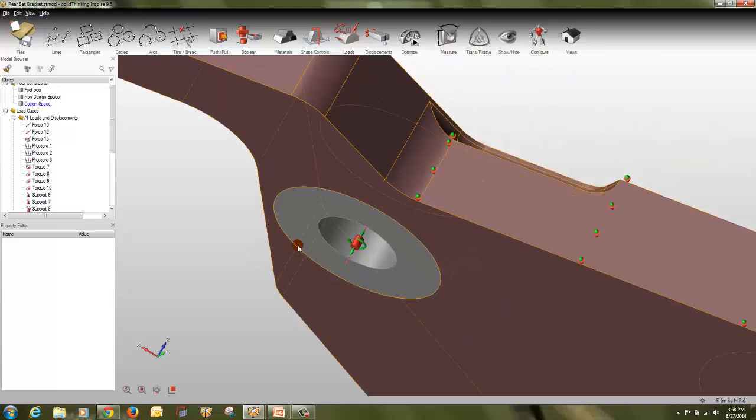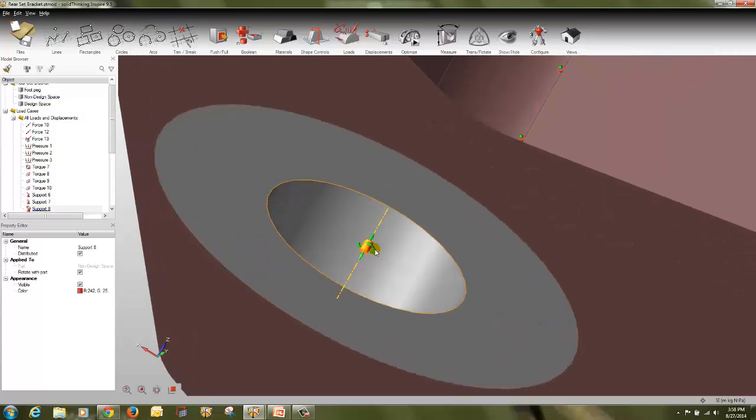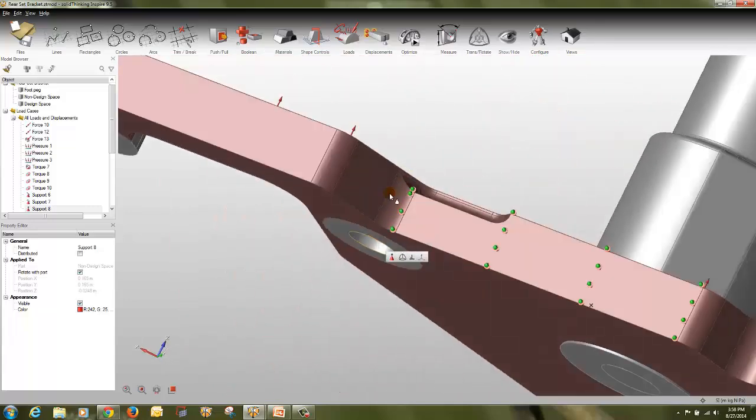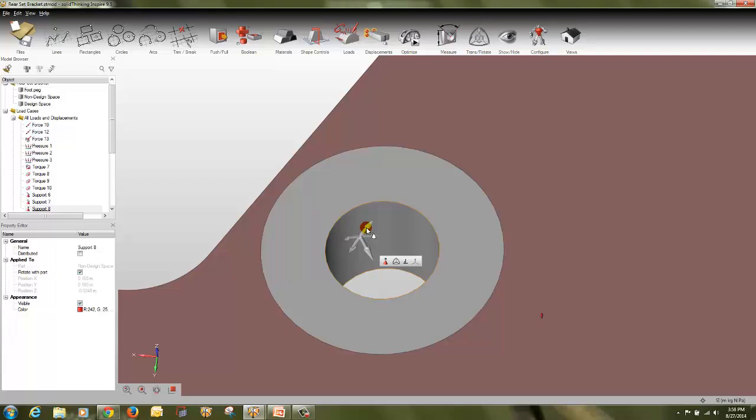So once I right click, this component is free to rotate and translate. But if you want to turn off, you can turn it off. So now translation and rotation are locked. It is constrained to translate and rotate in this particular direction. Point. You can change it like this. So point, you want in some direction.